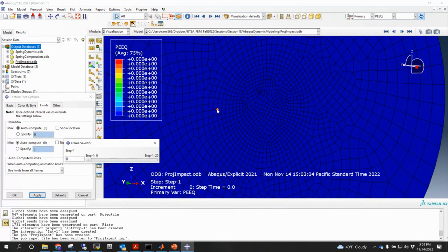And of course, with better mesh, being more thorough in terms of the mechanical properties. Once you hit something with really high speed, you have something that we call strain rate hardening effects. When you pull something super quick, it's actually more difficult to deform. So it suddenly becomes brittle.